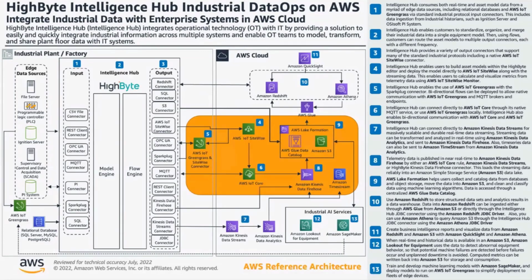It is important to recognize that data may also want to come down. Once you do your learning in the cloud, you may want to push information back down to the on-prem systems. In some cases, we've seen people push to the historian, to a PI historian. We've seen people push to a SCADA system. And in very rare cases, we're even pushing to PLCs with set point adjustments.